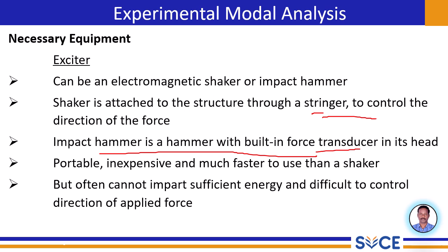It is portable, inexpensive, and much faster to use than a shaker. You don't need to set up elaborate fixtures to attach it to the structures. You simply strike the point you want to excite. This makes it a very efficient tool for quick modal surveys, especially on large or difficult to access structures.